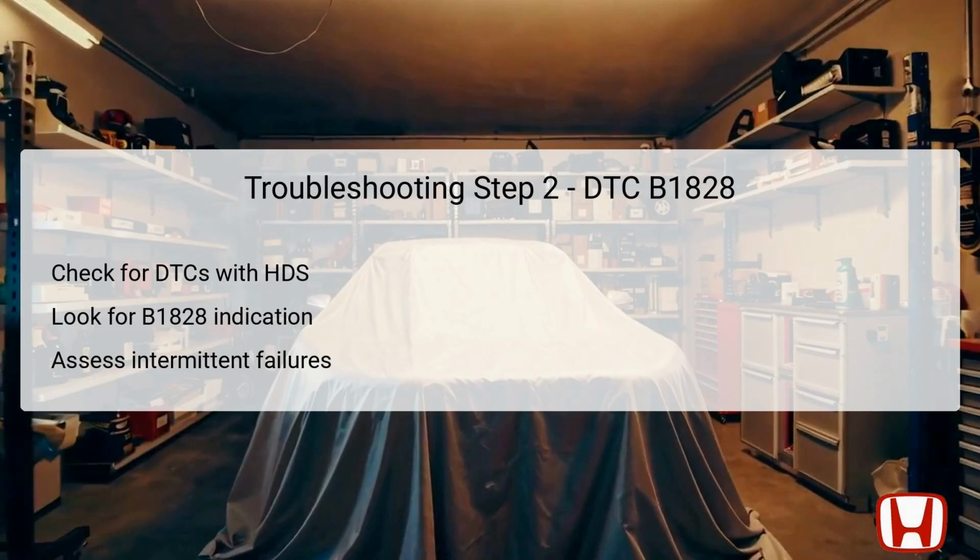During this phase, it is essential to examine all electrical connections for looseness or poor contact, as these can lead to sporadic failures. As part of the third troubleshooting step, again check for diagnostic trouble codes using the Honda Diagnostic System, HDS. In this instance, you specifically want to see if DTC B1836 is also indicated.